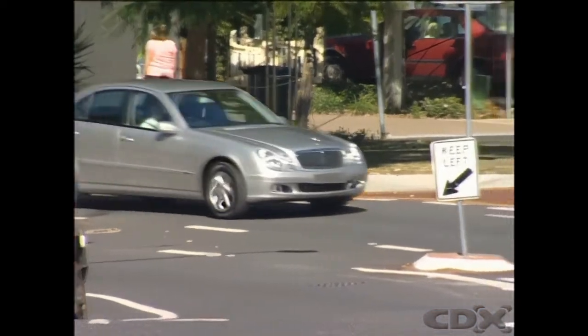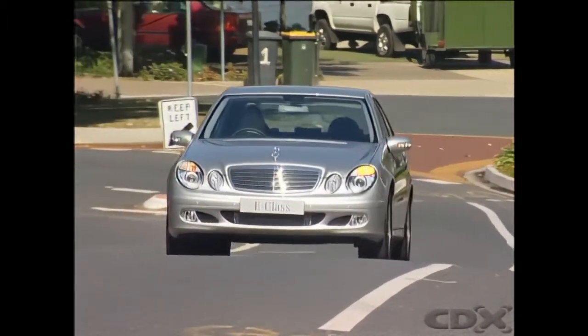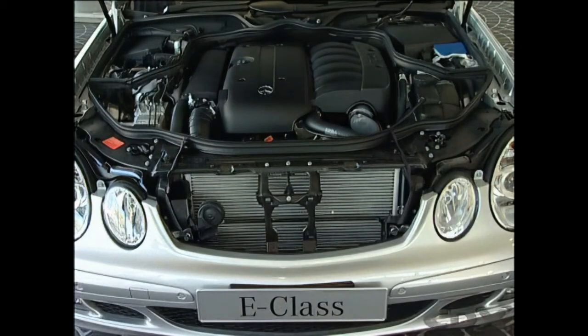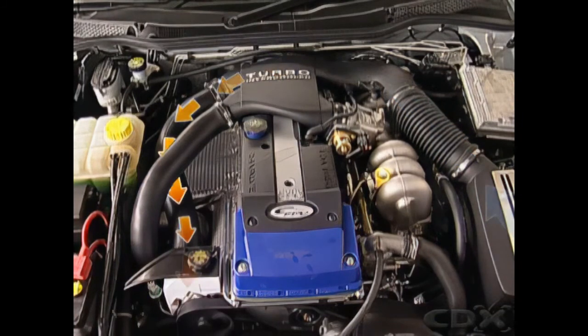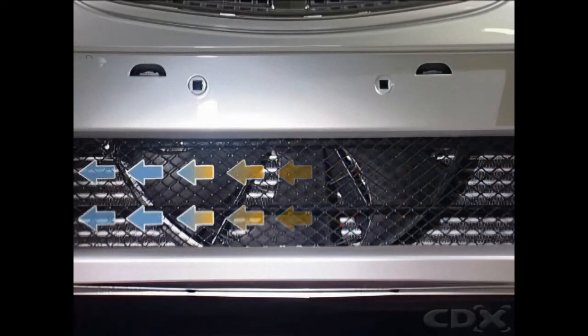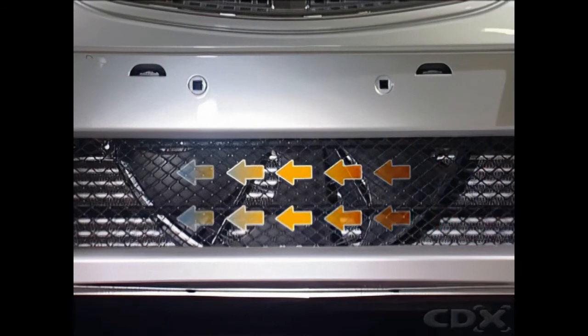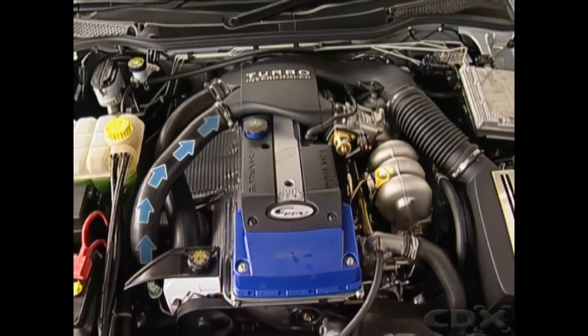The purpose of an intercooler is to reduce the intake air temperature by up to 390 degrees Fahrenheit, or 200 degrees Celsius, before it enters the intake manifold. This increases the density of the pressurized air and improves engine efficiency. The intercooler works at its most efficient when the turbo boost exceeds 15 pounds or 100 kilopascals. At lower pressures, there are still enough oxygen molecules in the air to provide for complete combustion of the air-fuel mixture.